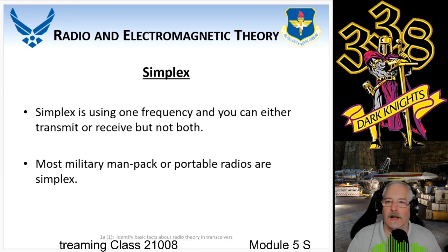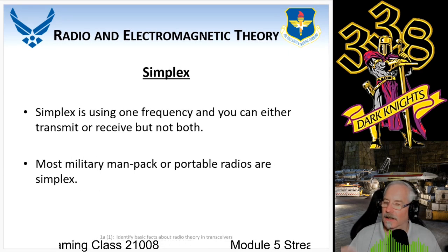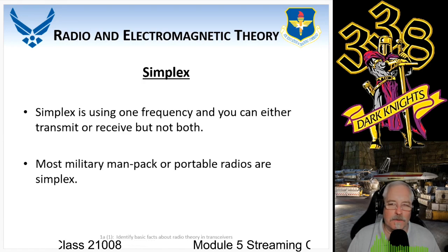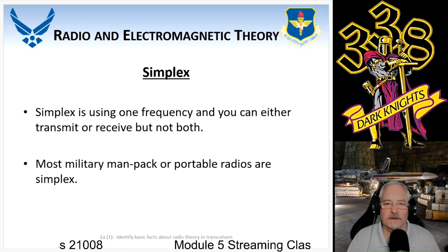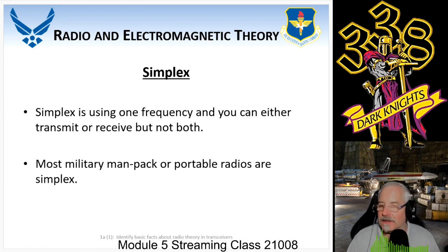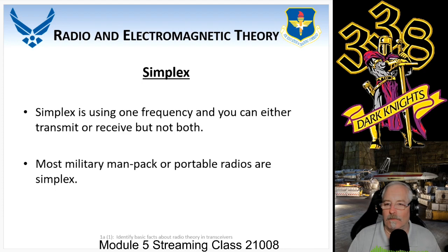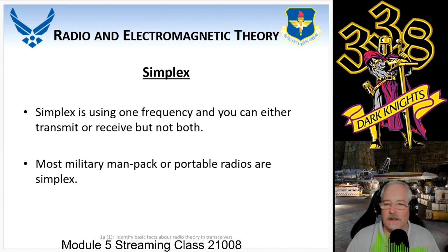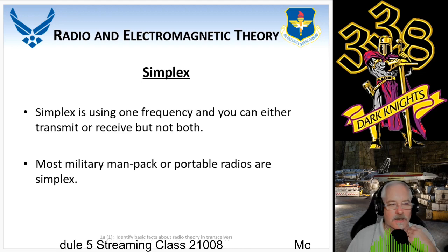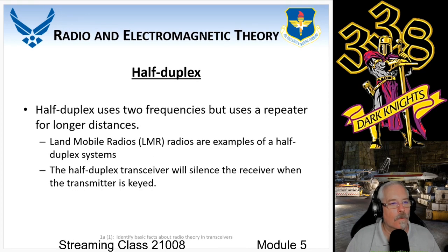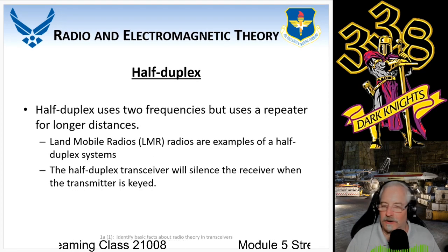First one is simplex, and I'm not familiar with your electronics. Did they ever talk about simplex to you? No, sir. Simplex is basically using one frequency between transmit and receive. Most of the time, your LMRs, your backpack radios, anything that's portable does that. We call that simplex. One frequency, either transmit or receive.